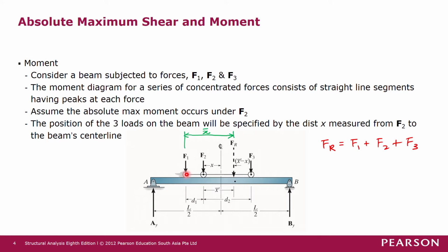If I use this point as the reference point, then I just find out the moment caused by each of the forces with respect to this point. The moment caused by all these F1, F2 and F3 about this point must be the same as the moment caused by the resultant force Fr multiplied by the distance x bar to this point. This is something that you have also learned in engineering mechanics.